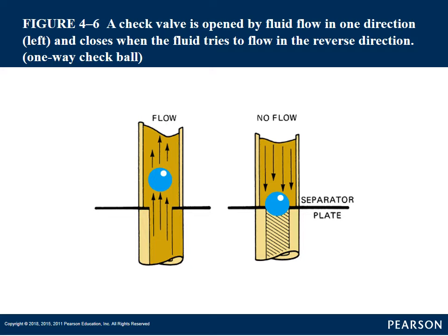So that would be the left side. That's actually exhaust. So the pressure runs out of that clutch pack. Well, they want to get it out of that clutch pack as fast as possible. So it'll push that check ball off because it's coming from the other direction. And it'll go through that bigger hole and exhaust the fluid quickly.